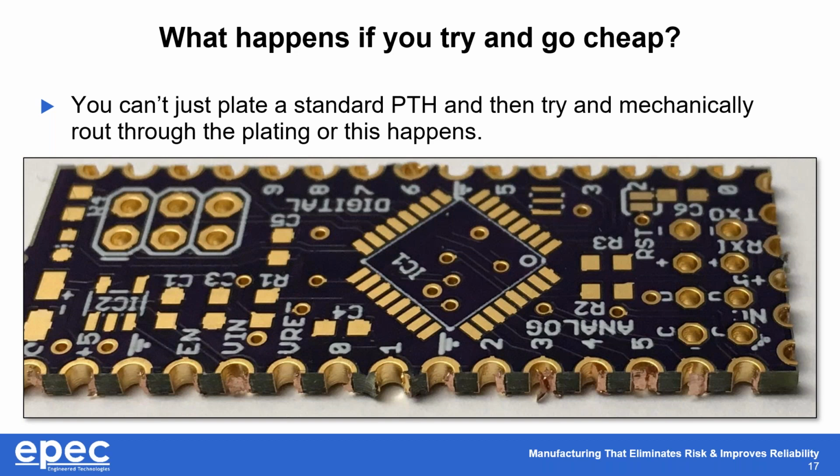And we've even seen many fabricators try to score through many of these types of boards and create more of a problem. The one thing that many customers don't recognize is, if you try to use this method and you want to run the router bit around the outside of this board, the bigger problem is that right here, to the right of the center of this, is where the router bit plunged in the first time. So as you're going around this rectangle, everything is great from a dimensional standpoint, because you still have enough of this little piece attached to the base laminate itself that it's not going to move.